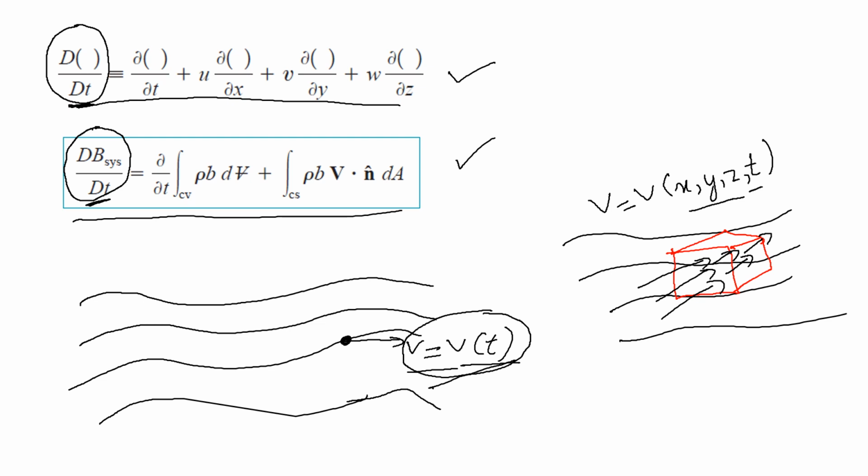And now these two equations link to this, the right hand side. If we look at the right hand side of the material derivative equation, we see a partial change in a certain property in time and in position. This is the local change, this is the convective change. So we are seeing these changes both with time and position. This is what the Eulerian description tells us, that we see a certain property both as a function of position and time.